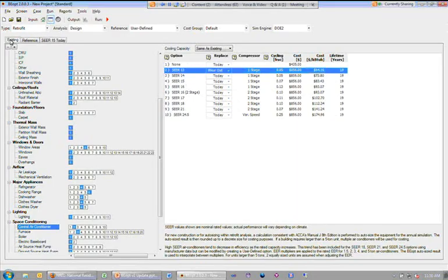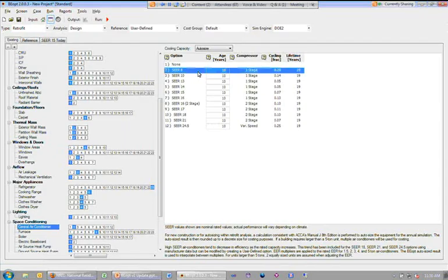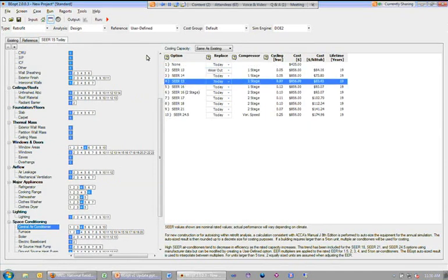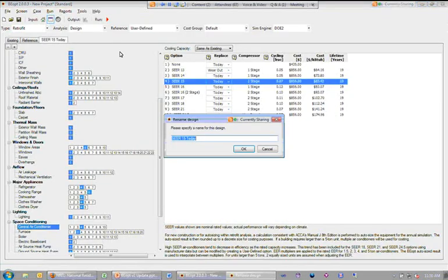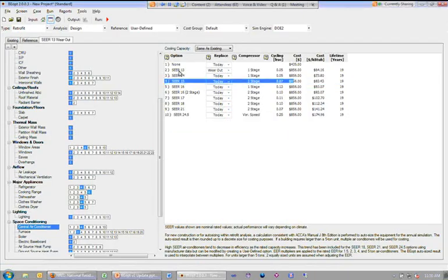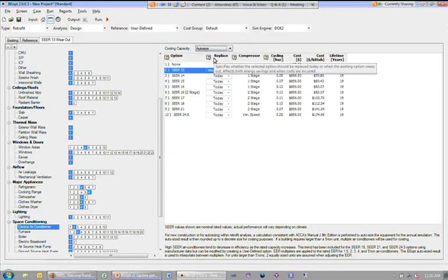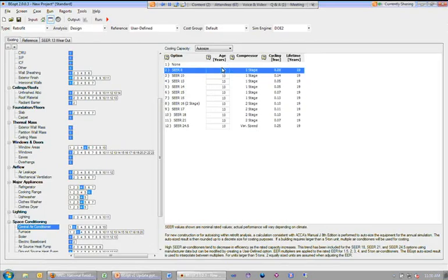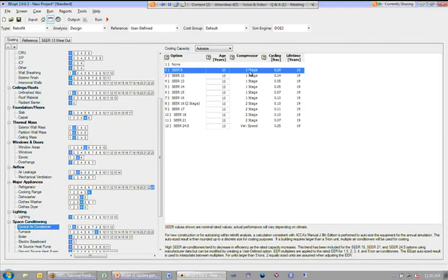I think we have it right now. So we have an existing air conditioner of SEER 8. Let me go back and rename this to call this SEER 13 at wear out. I'll stick with that. So in this situation, if we were to pick auto size, what we're going to have is 9 years remaining life, the difference between the lifetime and the age of the SEER 8 air conditioner.